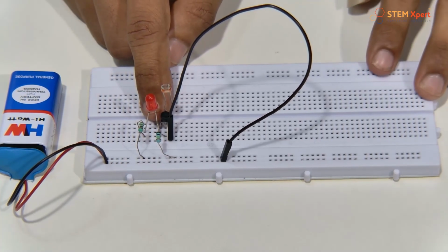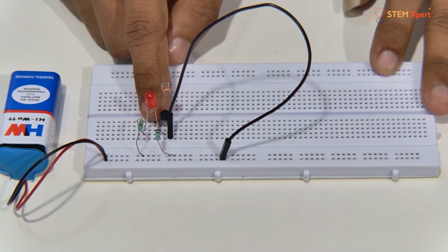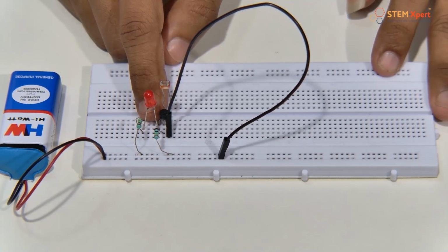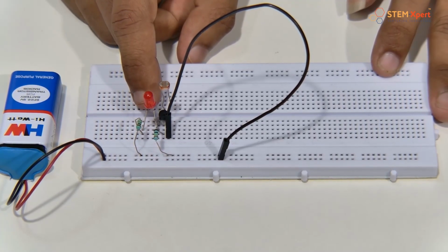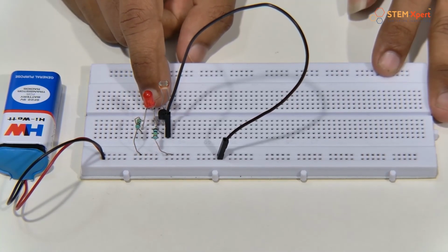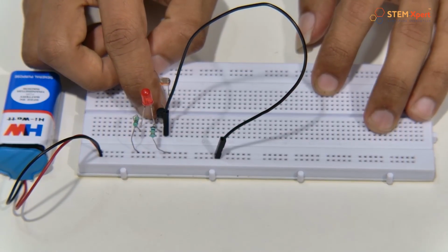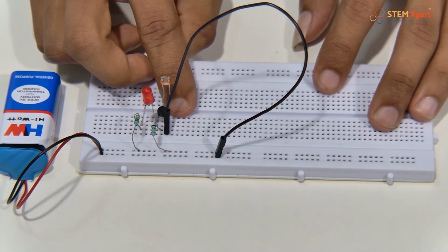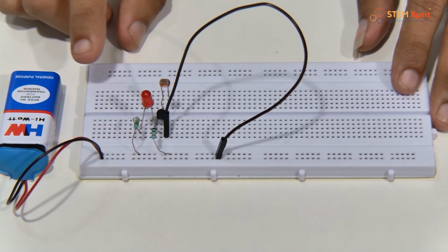So what about the transistor? Exactly, a transistor is used to amplify or switch electronic signals. Simply, we can say it is used in electronic switches to turn on and off. So what about the three terminals of our transistor? Exactly, it has three terminals, that is collector, base, emitter. Also here we are using the BC547 transistor, and which is the positive lead of our transistor? Yes, the collector is the positive lead, the base is used to activate the transistor, and the emitter is the negative lead of our transistor. Also we learned about the breadboard, battery, resistor and LED.